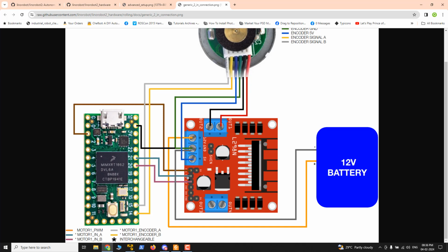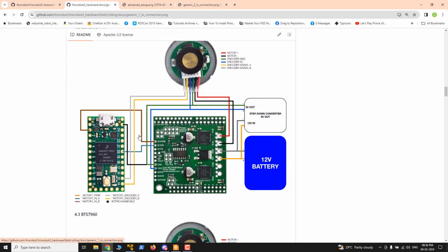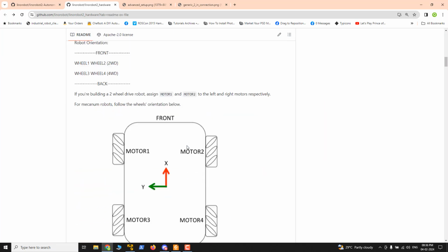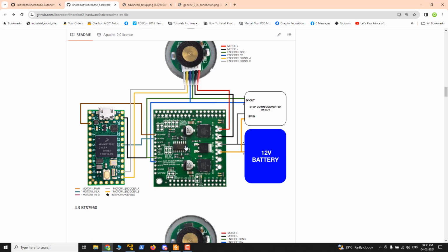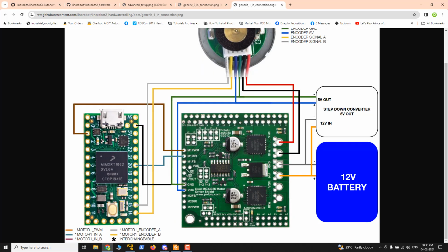There are certain pins that we can use or configure for PWM, and similar to that you can also watch this example, because they are showing multiple examples of motor interfacing. Here on the left side is the microcontroller, and each pin of the microcontroller is feeding the PWM, so that we can adjust the PWM, and thereby the motor driver will adjust the speed.